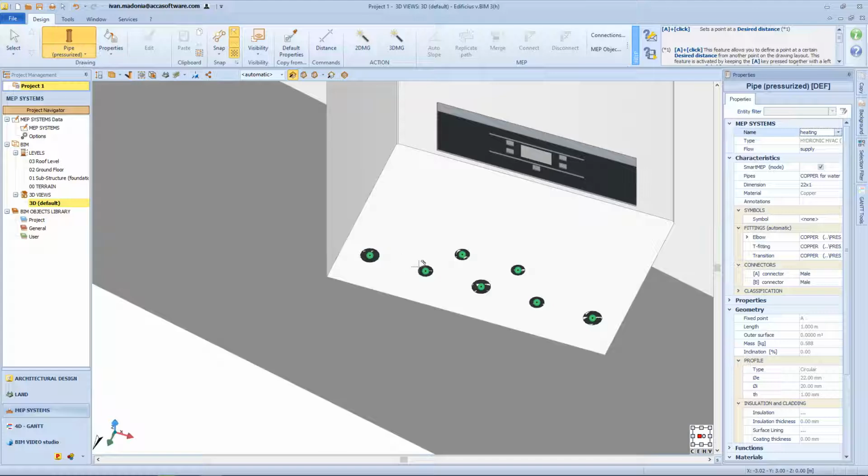These are snaps that appear on the connectors and specify any free attachments or connectors available to make the connection, although they do not identify the compatibility of the connection to be made. By placing the cursor in correspondence with a free connection, be it point or surface, the snap, previously colored green, becomes yellow, thus enabling the possibility of making the connection with a click of the mouse.